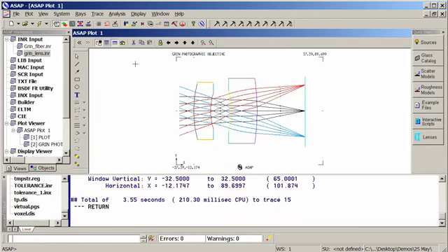And what we have is a photographic objective with a single gradient index component in it, this second lens, which you can see as the light curving as the rays propagate through the system. So again, whether you're talking about gradient index fibers where you need to propagate a wavefront, or a gradient index component such as a lens where ray propagation is the appropriate analysis tool, ASAP is fully capable of doing any type of analysis through inhomogeneous materials.